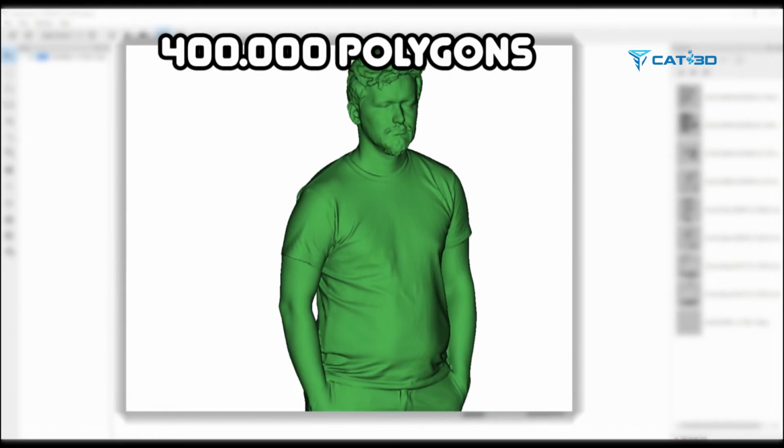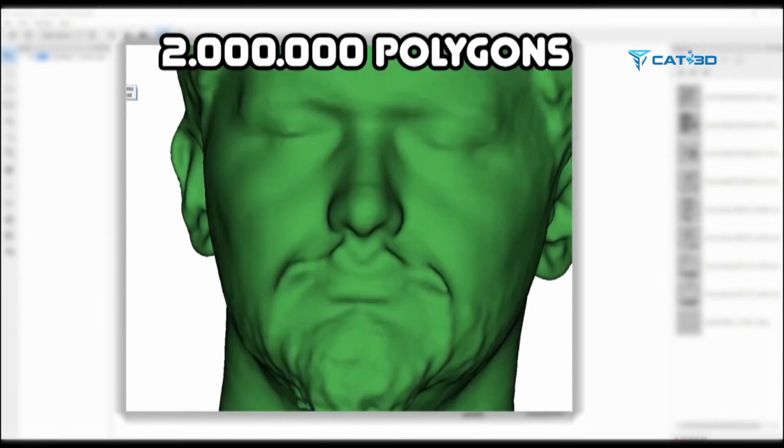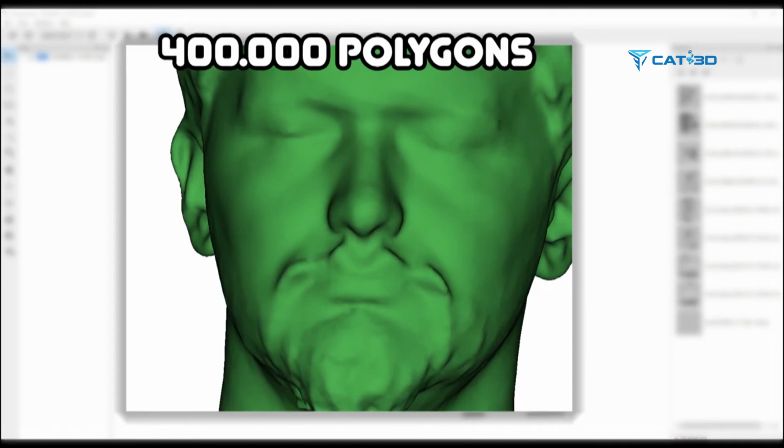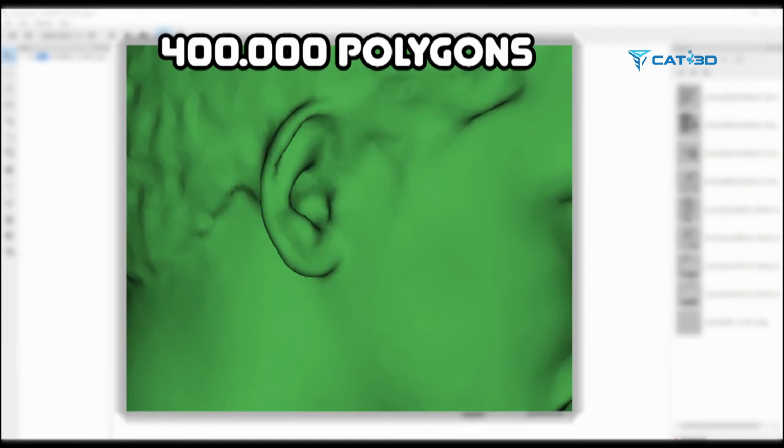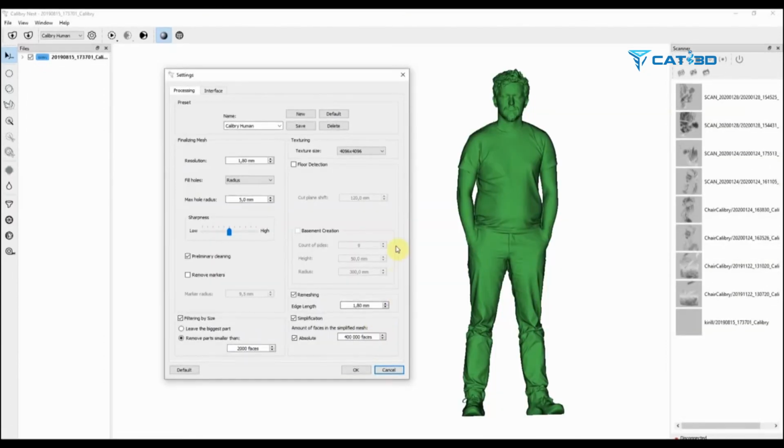If you're planning to put texture on your 3D model, we also recommend simplifying this model before texturing it, because it takes much less time than if you hadn't simplified the object. The faster you want to put texture on the object, the higher the level of simplification you should choose. Also, don't forget that simplification loses high resolution.